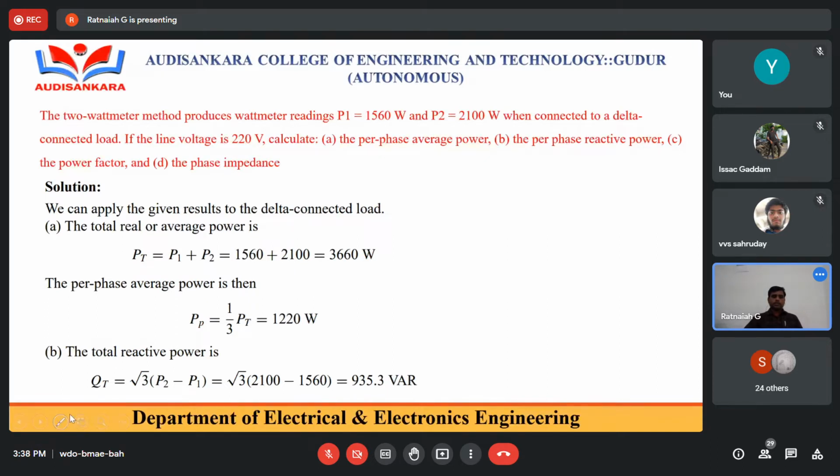Coming to the problems on the 2-wattmeter method, let us take a small problem first. What is the problem statement? We have to read out the first one. The 2-wattmeter method produces wattmeter readings. That is, there are two wattmeters used to measure the power. Wattmeter 1 reading is 1560 watts, and wattmeter 2 reading is 2100 watts, or 2.1 kilowatts, or 1.56 kilowatts, whatever, when connected to a delta connected load. So here both the wattmeters are connected for the delta connection.